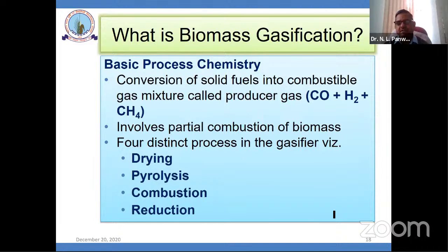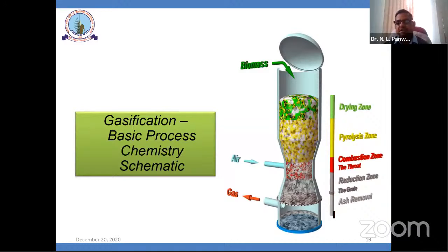So different kinds of biomass gasifiers are available, and IISc Bangalore people have done a miracle in producing simple electricity through biomass, with effective utilization of paddy straw to produce electricity through the gasification process. It is not easy to produce electricity, because the gas cannot be used directly in the engine. There is a considerable amount of tar and other impurities. And the temperature attained is higher, 1000 degrees Celsius. In combustion, whether it is partial combustion or complete combustion, it doesn't matter, the combustion process certainly leads to a temperature of 1000 degrees Celsius.